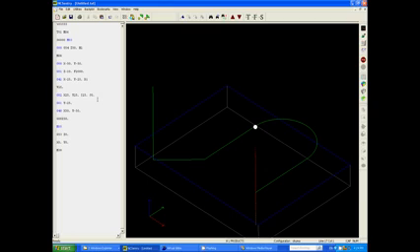assist the machine to work out the center of the arc that is going to be performed. Now, they are incremental, and with each axis X, Y, and Z, you've got I, J, and K. I very rarely have used the K. What they do is work in unison with each axis.